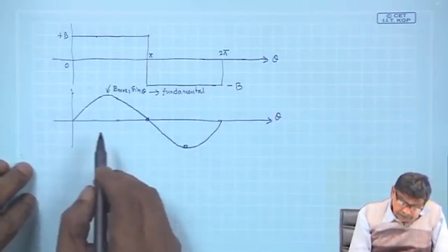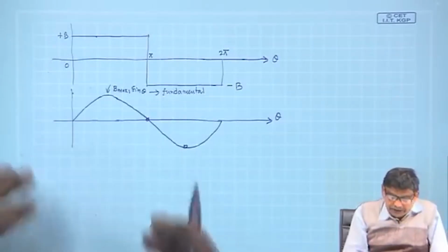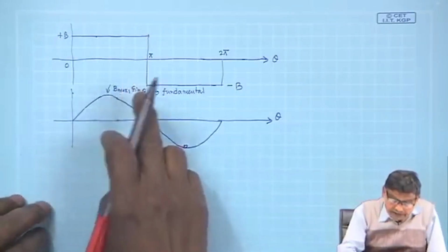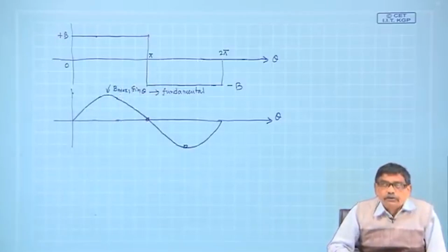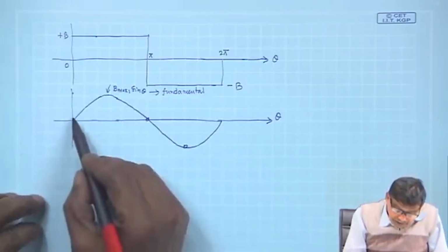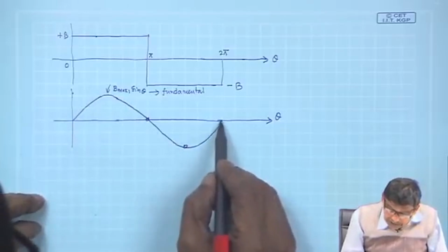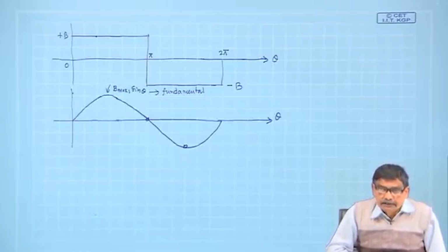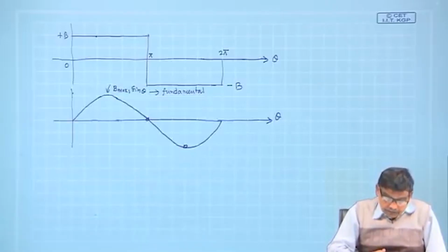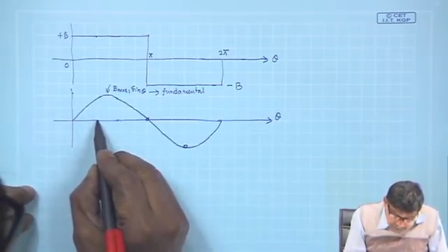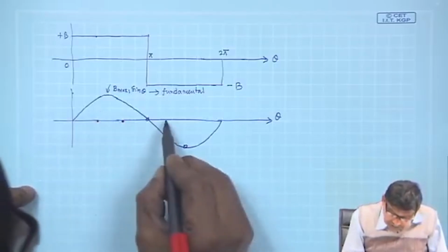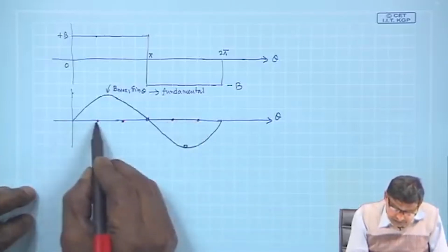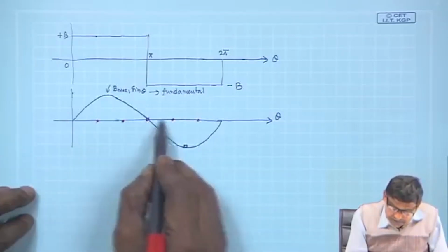Now, the third harmonic component. What is the third harmonic component? The third harmonic component B max 3 will also be sinusoidally distributed, but when the fundamental makes one complete cycle, your third harmonic will make 3 complete cycles. That is why it is called third harmonic. So, let me divide these things with 60-degree intervals. Each one is 60 degrees, this red marking, this is 60, 60.